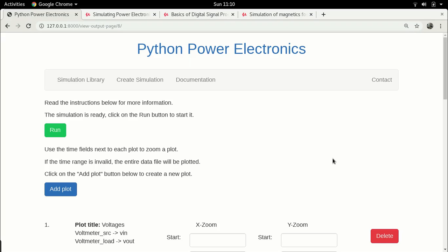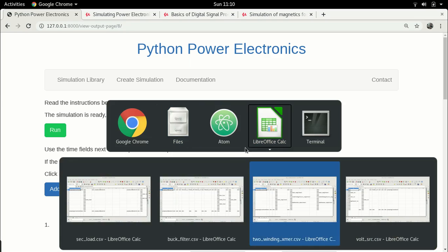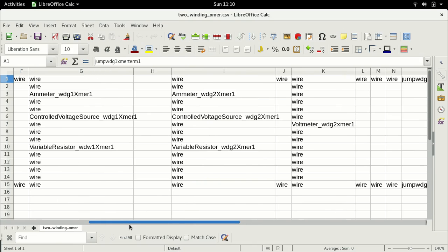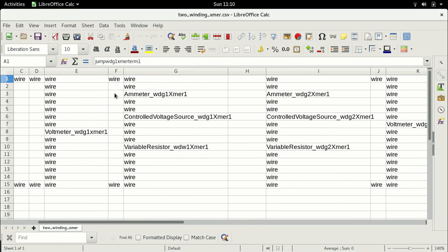So hello everyone and welcome back to this next lecture in the DC-DC converter series, and this is where we had left off in the previous lecture where we were running the flyback converter. Specifically, if we go to the circuit, the difference was in changing the polarity of the secondary winding of the transformer. So we had reversed the polarity. If there's a dot polarity in the primary on the top terminal, the dot polarity on the secondary is at the bottom terminal.